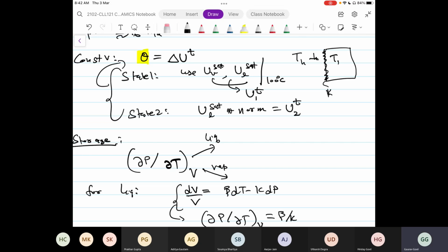So now can you model the flux from outside to inside given these two resistances? Yes, sir. Okay, and from there you can estimate, given your insulation, given TH, given T1, how much time it will take for Q amount of heat to be added, which you have just calculated here. Okay, let's say the time is 5 hours.